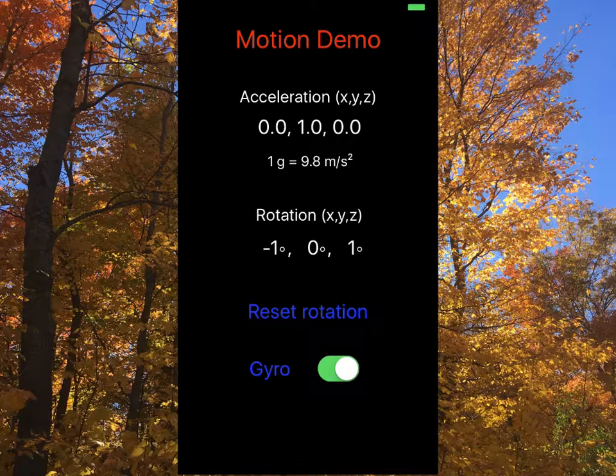Okay, I'd like to continue the demo with a little bit of an experiment here. I have the iPhone turned upside down against a horizontal and vertical surface. Now you'll notice that the Y component is 1. There's been a little bit of jitter in the rotation since I started the application and the recording. What I want to do is rotate the iPhone against its one corner till I hit a z-axis of 45 degrees. Rotation around the z-axis.